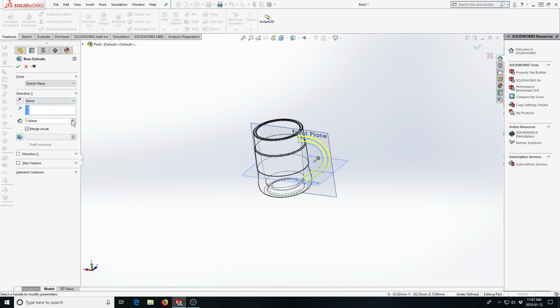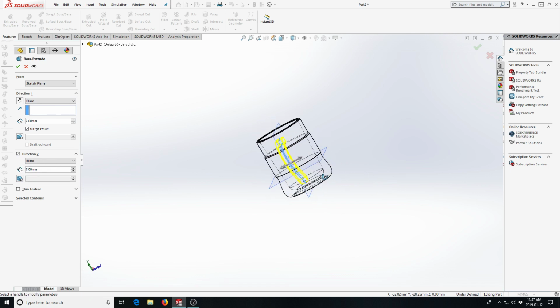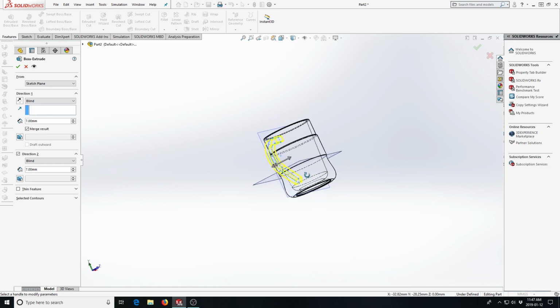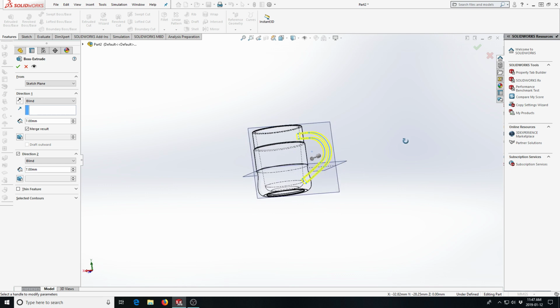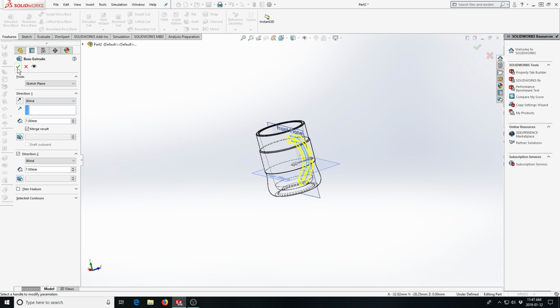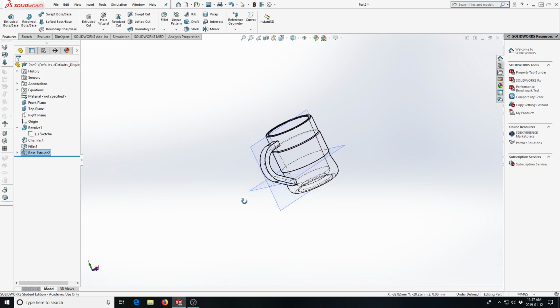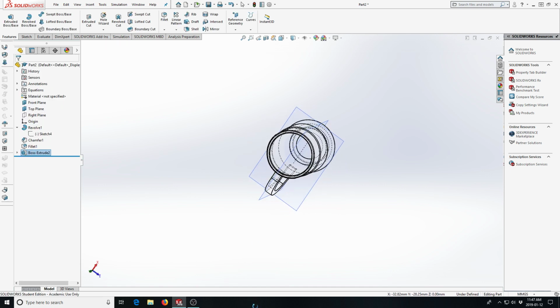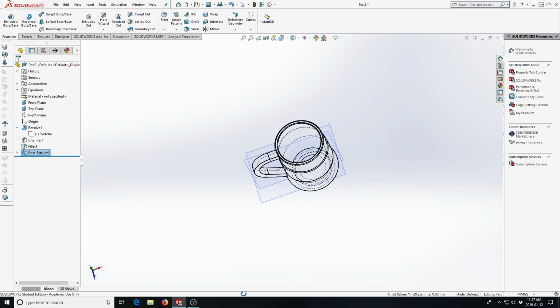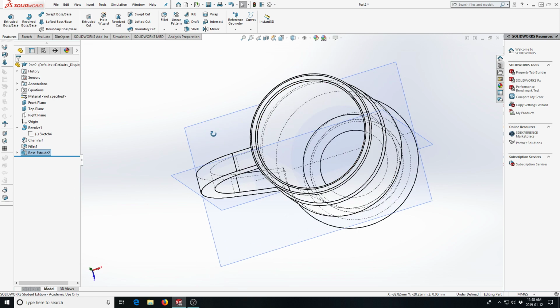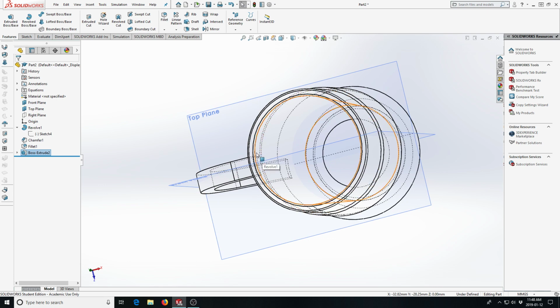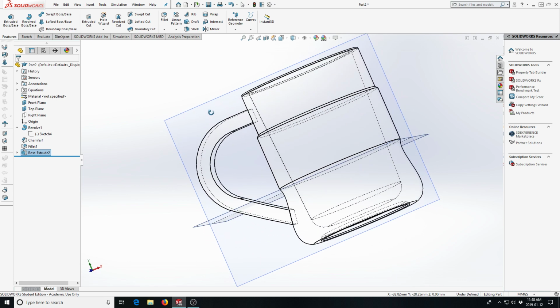So I can make it direction 1 7 millimeters. I can make direction 2 also 7 millimeters. So that will extrude equally in 2 different directions. What do you think? Not too bad. So there, my coffee cup has a handle. I've made it so that it doesn't project on the inside. One of the problems you'll get into is if you do it this way, you'll find the inner surface, you'll pierce it with the handle projection, and that's not so pretty.